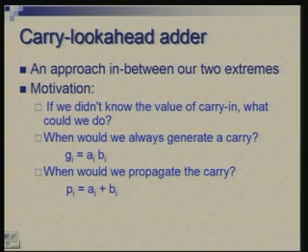So, why not we take an approach which is somewhat in between. We do want to have look ahead, we want to directly compute the Ci's without looking at intermediate carries. So, what we can do is basically allow some pre-processing to be done on Ai and Bi. We look into what role Ai and Bi are playing in determination of carry and try to do something before we really compute all the Ci. So, we have actually 2 stages.